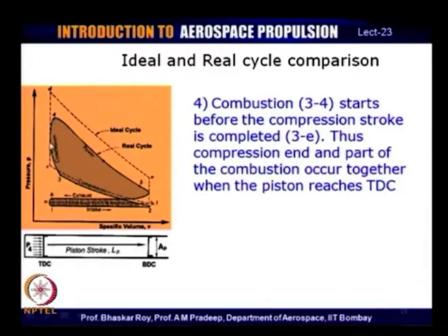So, the process of combustion, as you can see, quite often, due to incomplete combustion or due to the movement of the piston coming in the way, never quite finally reaches the point D. Somehow or other it finishes off somewhere around 4, and then the process of expansion, or the power stroke, starts.